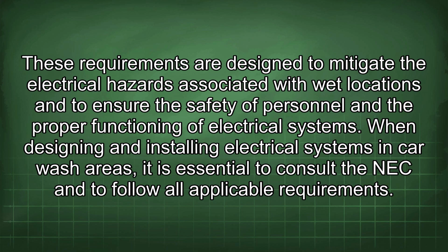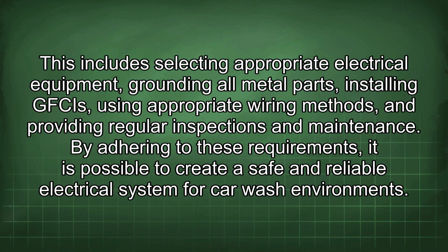When designing and installing electrical systems in car wash areas, it is essential to consult the NEC and to follow all applicable requirements. This includes selecting appropriate electrical equipment, grounding all metal parts, installing GFCIs, using appropriate wiring methods, and providing regular inspections and maintenance. By adhering to these requirements, it is possible to create a safe and reliable electrical system for car wash environments.